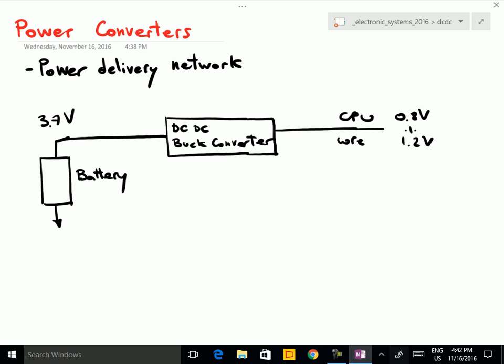Of course, you remember that the power dissipation is proportional to the clock frequency, and is proportional to the square of the supply voltage. Therefore, if you are able to reduce at the same time the clock frequency and the supply voltage, we can strongly reduce the power consumption. And this is typically done especially for the microprocessor, which is one of the blocks which is dissipating the most power.